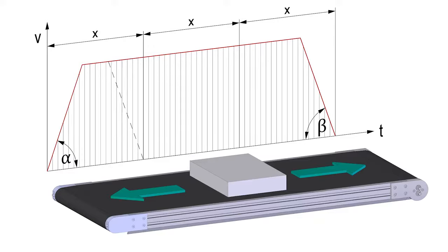In this case, the belt rotates to the right, so DIN 1 has the value low. Via the digital input DIN 2, you specify how often the previously set transport distance is to be executed. The distance is executed once via a positive edge. With each subsequent low-high edge, the entire positioning distance is extended by the set distance.